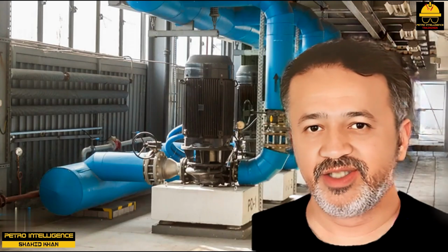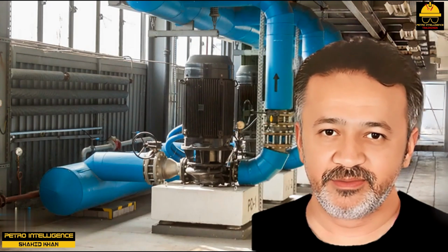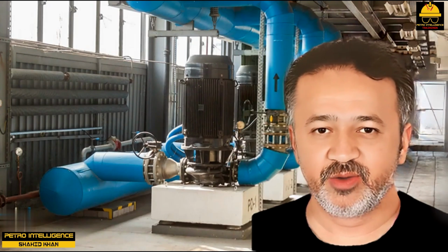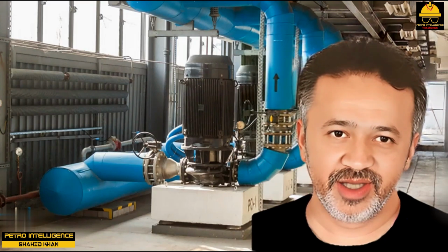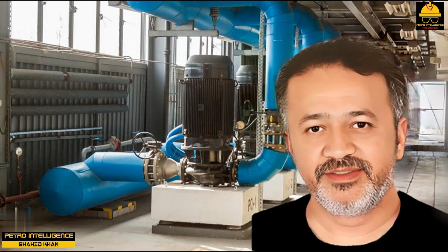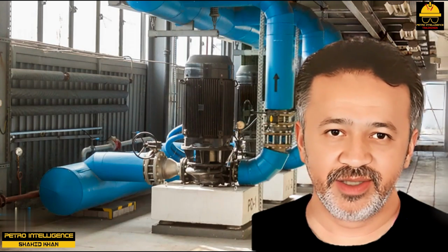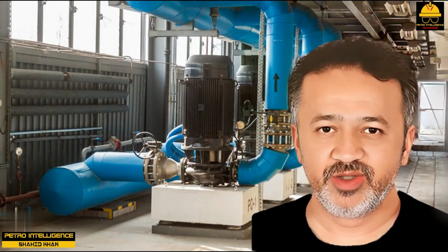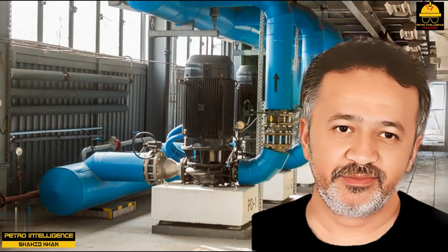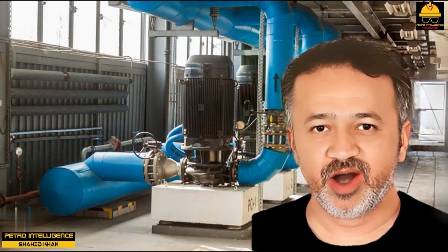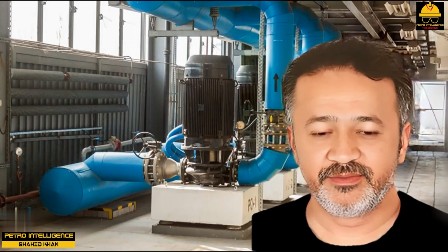About 250 years ago, Daniel Bernoulli first noticed 2 important things about energy. Energy in one form can be converted to energy in another form. While energy can be changed from one form to another, it cannot be created or destroyed. This idea of the conservation of energy is at the heart of any process plant. In the case of the water treatment plant, the reduced velocity of the water was converted into feet of head. That is, the elevation of the water in the sump suddenly increased and blew the manhole covers off the top of the sump.